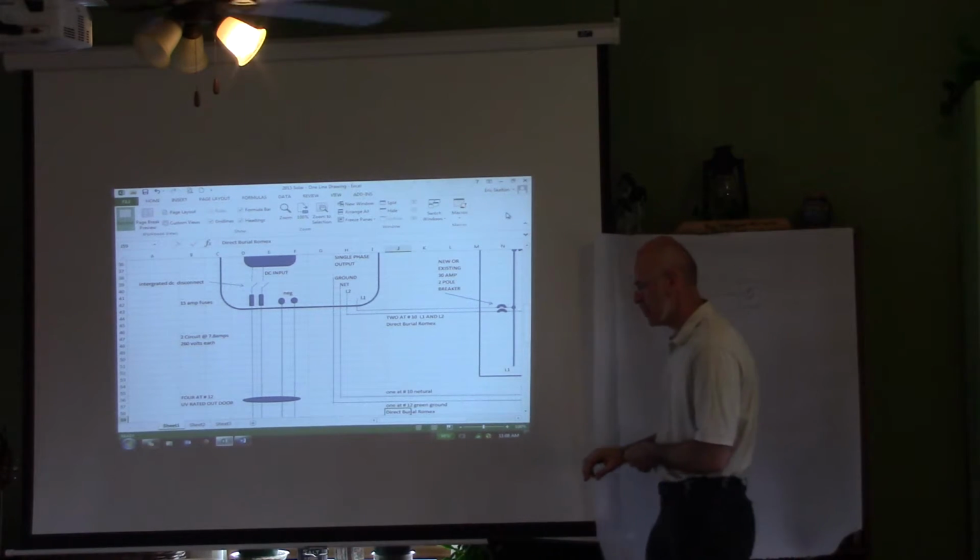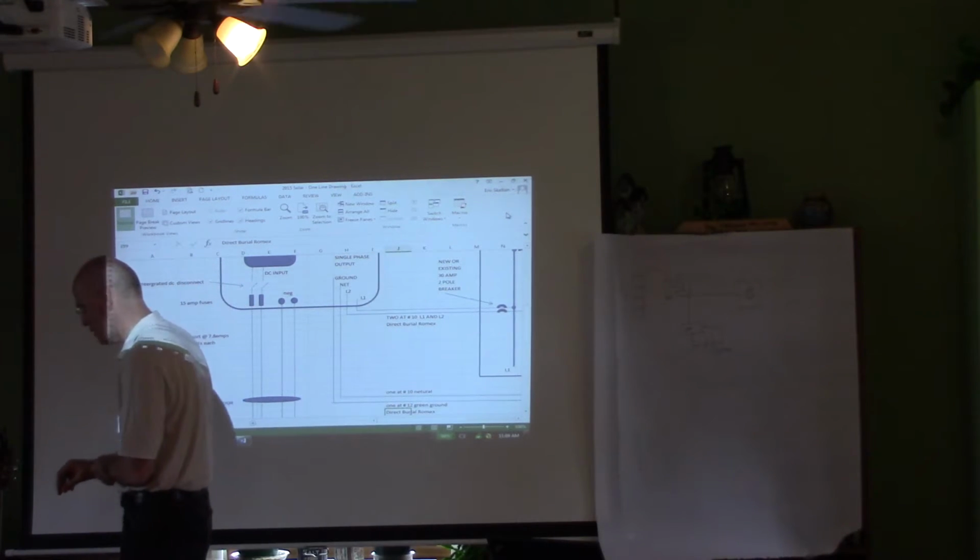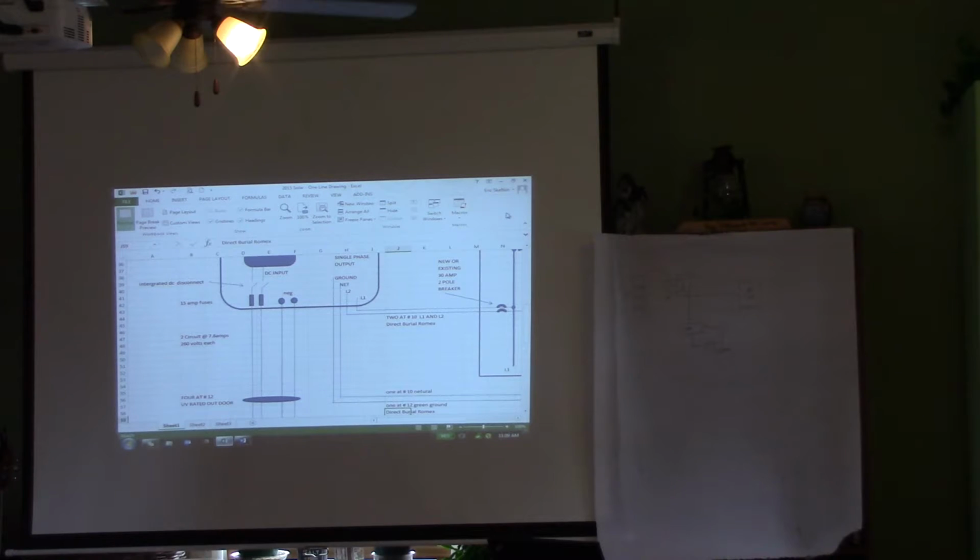You can only discharge a deep cell battery about 50%. Batteries are sized in what's called amp hours. So if you had a 1,000 amp hour battery, you could really only use 500 amp hours out of it, before the voltage goes from 12 volts down to like 9. You can take it down to 12 down and still function. The inverters will still function, but you have to keep the inverter happy. It needs a voltage threshold. Is this the kind of information you were looking for?